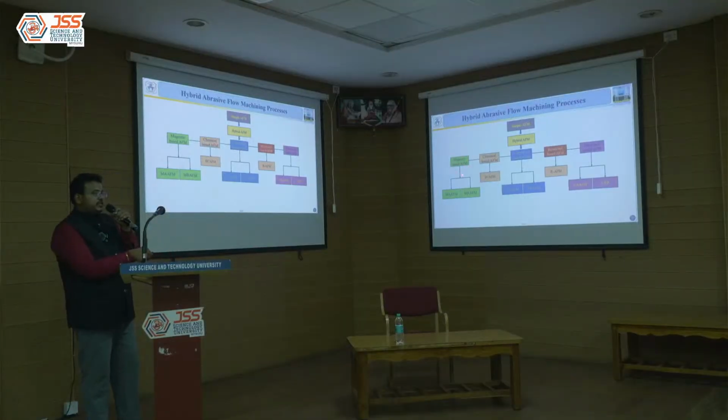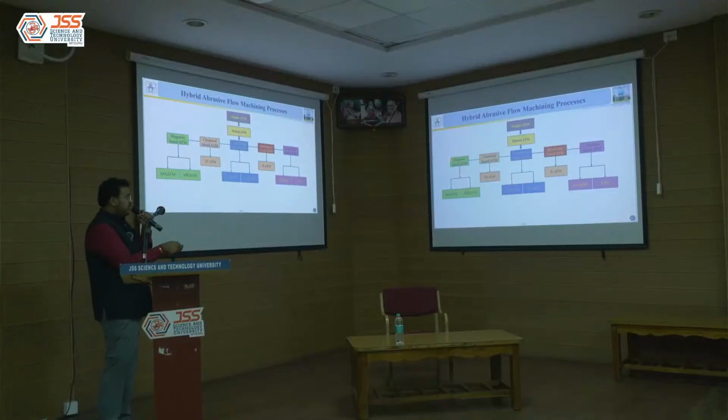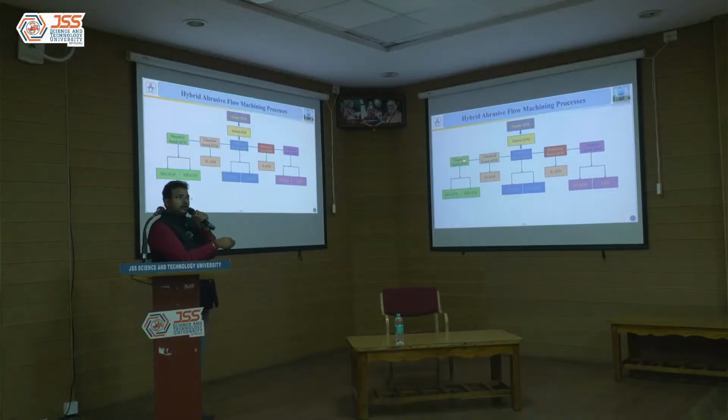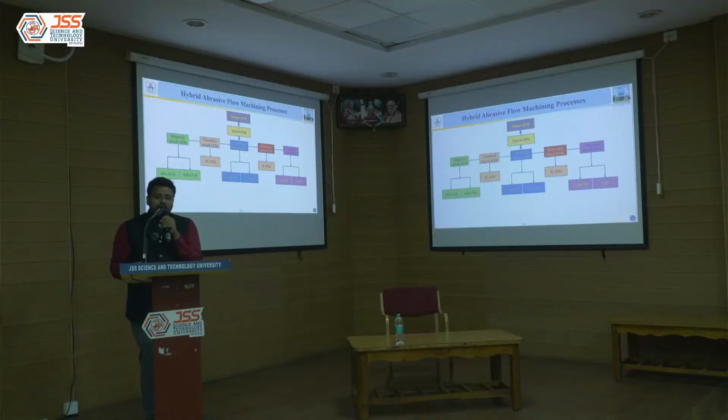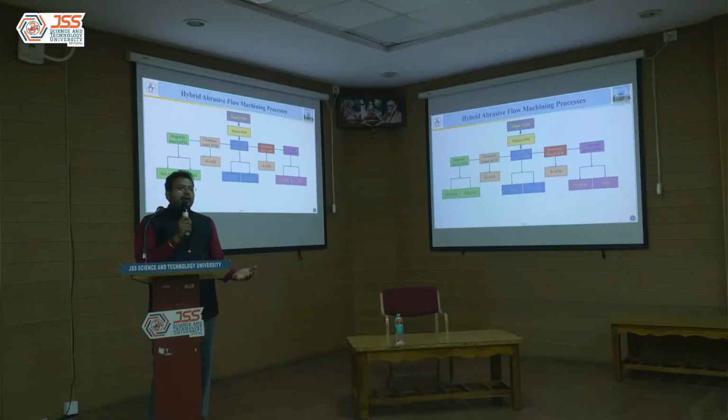Magnetic based abrasive flow machining. There is one PhD on this. The scholar from IIT Roorkee applied a magnetic field around the tooling. He mixed the abrasive particles with iron carbon particles, and when the magnetic field is applied, he studied the performance of the media on magnetic materials as well as non-magnetic materials.